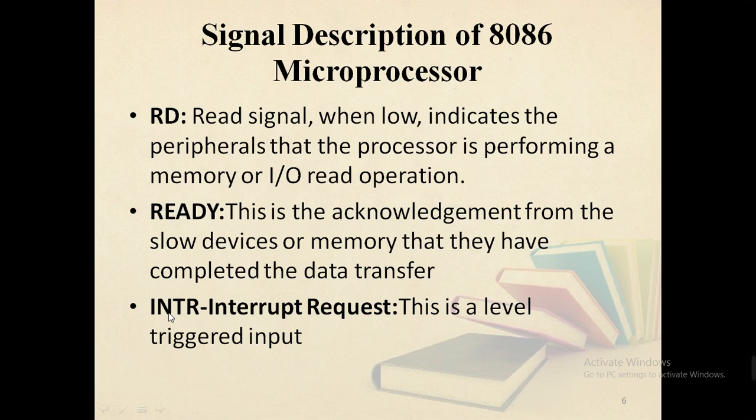Next, INTR, interrupt request. This is a level triggered input. This is sampled during the last clock cycle of each instruction to determine the availability of the request. If any interrupt request is pending, the processor enters the interrupt acknowledge cycles.